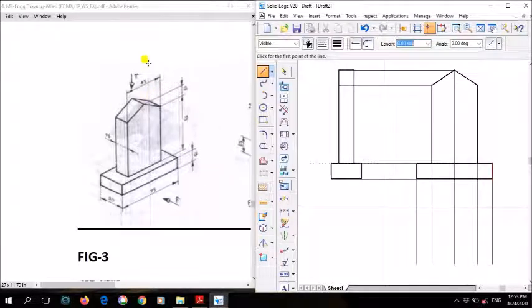Clear? So now we need to draw the top view. In the top view, this plane, the bottom base is visible, that is 75 by 30, and this one, this plane, that is 45. Here you can see there are two faces visible. These two faces are divided at a center point. You will get a line like this. Means you need to draw two smaller rectangles. And its width should be how much? That is 45 mm. So what you have to do is same way like earlier.